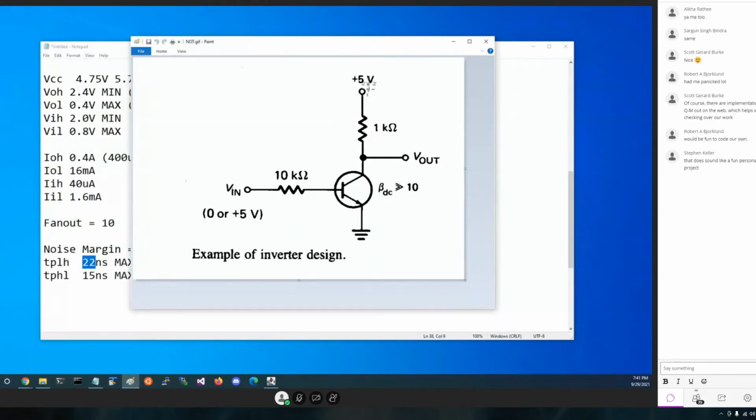But here's the idea. We have plus 5 volts applied to the top of this signal line. We have the signal coming in applied over here. If you think about this, if we put an LED and a battery over here, this is the same as the circuit we've always been using. Put a battery over here, that's the one I said we're going to replace eventually. Well, if we have a beta in the transistor that's much, much greater than 10, then the current through a resistor that's 10 times bigger than that one will certainly, when multiplied by beta, be bigger than the current that's limited by that. And will certainly, when this is made high, put this transistor into saturation.